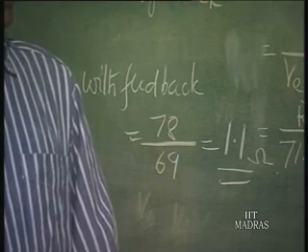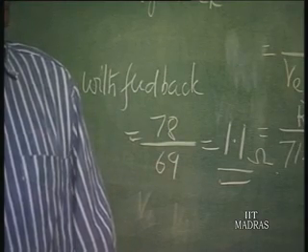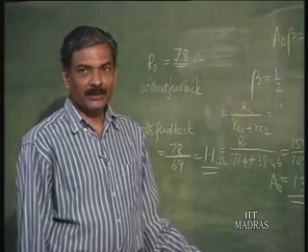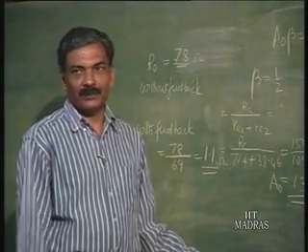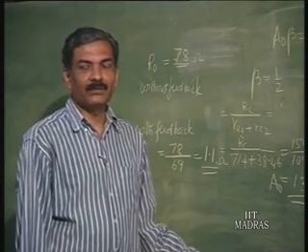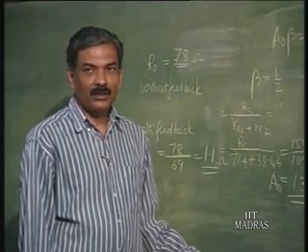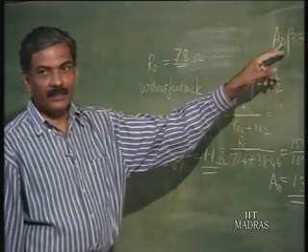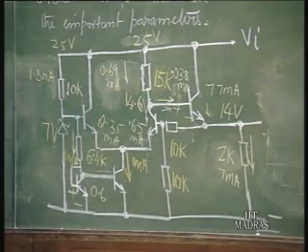One thing that you have to remember is that this is a feedback structure, and that is why it is giving pretty low output impedance. If you use an op amp, it can become fractions of ohms, but that is valid only for low frequencies. At high frequencies, you cannot assume this kind of gain, the loop gain reduces and output impedance increases.